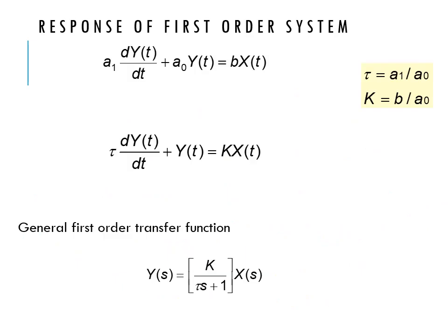Alright, after you replace the deviation variables into the subtraction equation that you got before, you will get this equation. We name it as equation 3. So equation 3 is the general linear first order differential equation in terms of the deviations of the input and output variables from their initial steady state value. So it has three coefficients, which are a1, a naught, and also b.